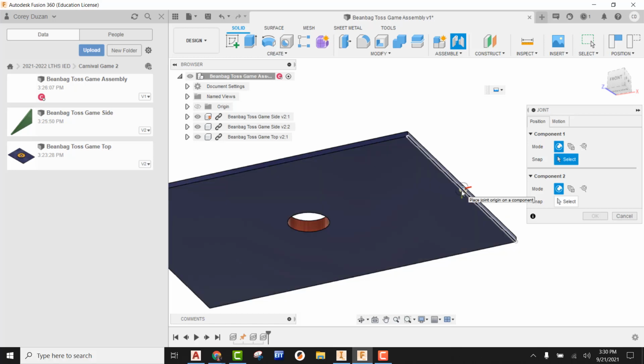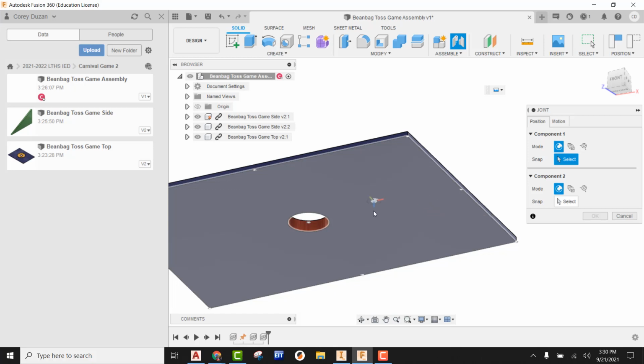Once you get over to different points, then it's going to start adopting different characteristics, and that's what gets a lot of people in trouble. So what I tell my students to do is just start here at the middle of the surface, and I'm now going to hold down control on the keyboard, and now whatever point I go to, it's going to be aligned to that surface and how it originally looked. Okay, that's going to be super helpful.